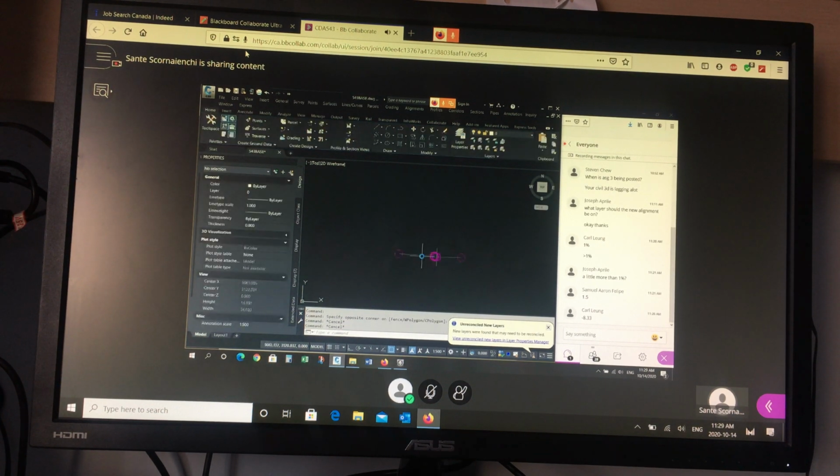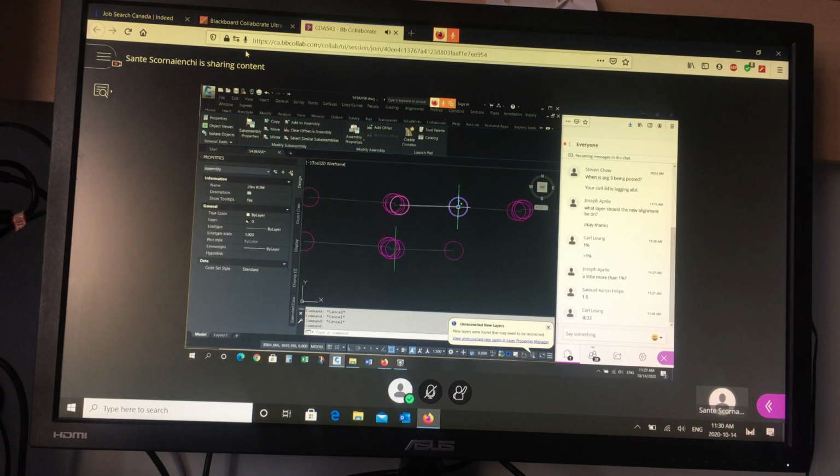So if you compare this, let me just move it. You don't need to do this, but let me just move it. I'm going to put it over here. If you compare it to this side of the road, right, this geometry is exactly the same as this. But in this one, the reference point is the crown, because the alignment represents the crown of the road. In this one, the alignment represents the gutter. Anybody notice any problems with this?